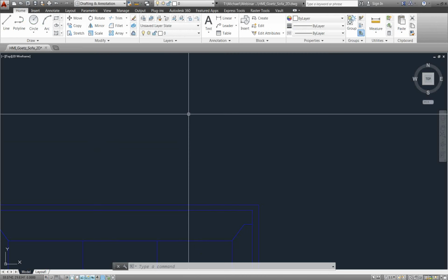like I want to zoom extents. I want to create a new layer called A-Fern. I want to then change all of these lines in my drawing to that layer, or maybe I want to change them to layer 0. And I want to run a purge and an audit before then closing the drawing and running the same steps through the next block.